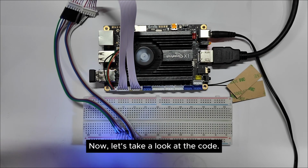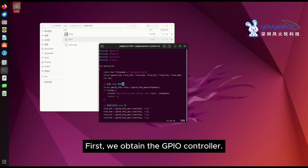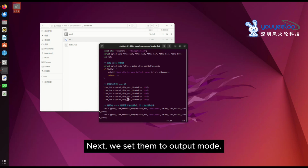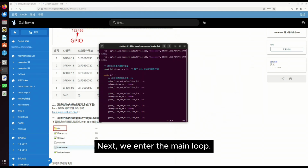Now, let's take a look at the code. We utilize the libgpiod library to control the GPIO pins. First, we obtain the GPIO controller. Then, we acquire the corresponding GPIO lines. Next, we set them to output mode. Next, we enter the main loop to implement the running light effect.